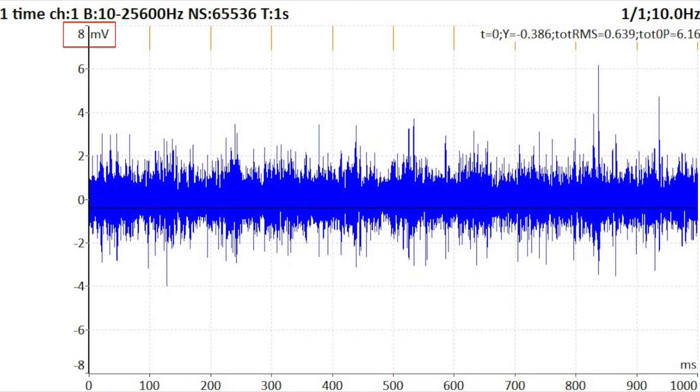If we used 16 bits resolution for the full plus-minus 12 volts range, then the step is 0.3 millivolts. The signal maximum amplitude is 3 millivolts. It means we would use just 10 positive stripes and 10 negative stripes. The signal would be distorted.